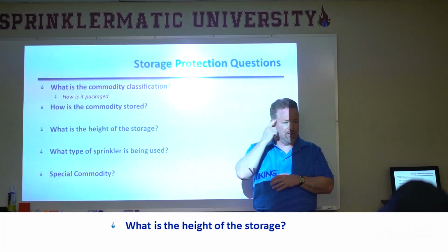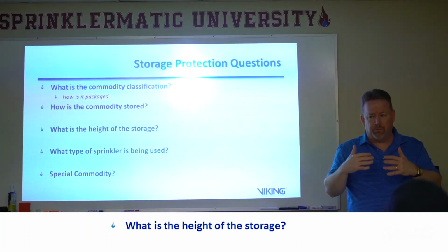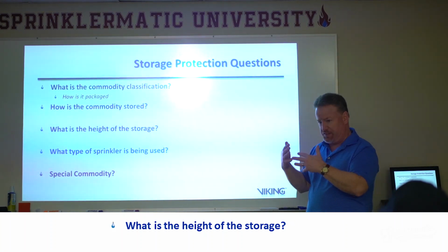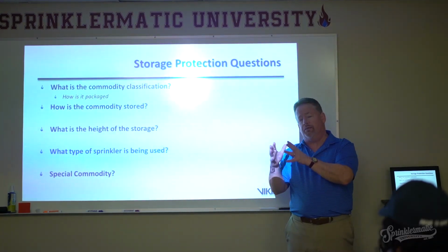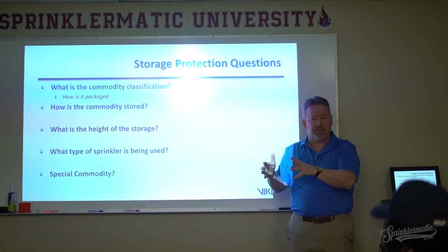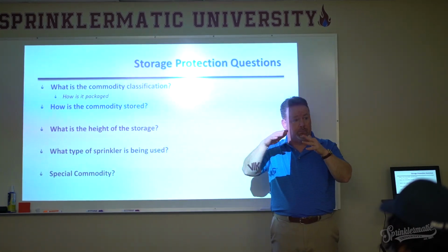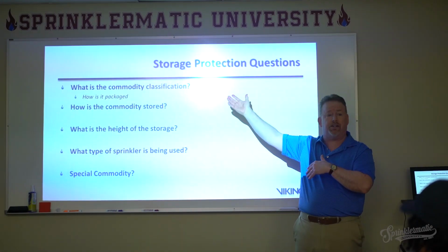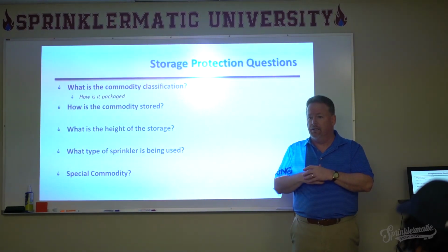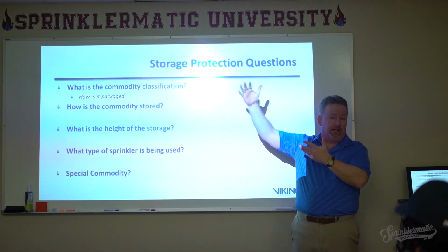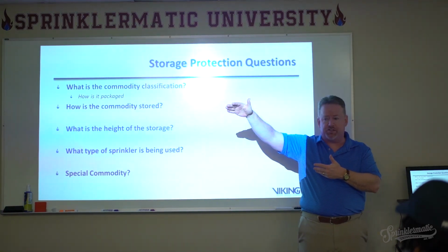How high is the storage? When we start to look at the specific chapters that deal with storage protection, we're going to see that we divide this off into, is it more than 12 feet? Well, that's this type of storage. Is it less than 12 feet? Well, then that's this type of storage. Is it on racks, and how high are those racks? Well, that's going to have an impact on your overall sprinkler system design.